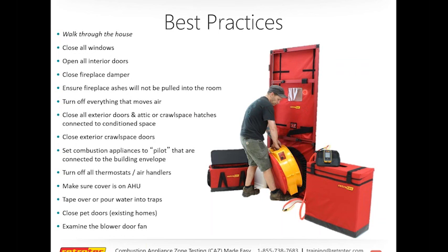In fact, one of the things that I used to like to do is set up the blower door, set up my reference tube, get everything perfect, and then it's just a matter of changing a couple of tubes between the two tests. So it's very simple, and it saves a lot of time.